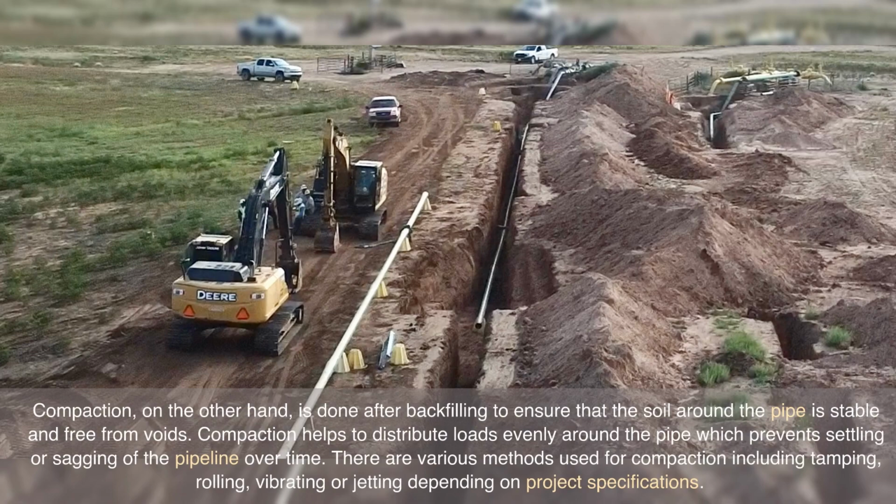Compaction, on the other hand, is done after backfilling to ensure that the soil around the pipe is stable and free from voids. Compaction helps to distribute loads evenly around the pipe, which prevents settling or sagging of the pipeline over time. There are various methods used for compaction, including tamping, rolling, vibrating, or jetting, depending on project specifications.